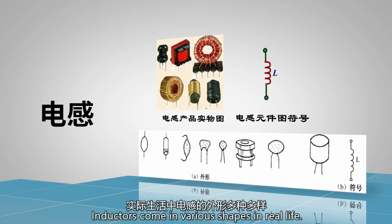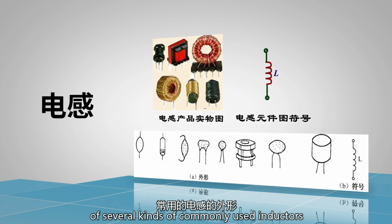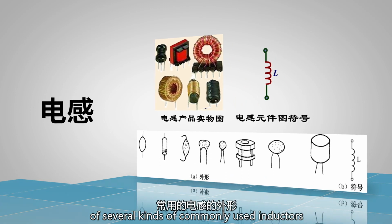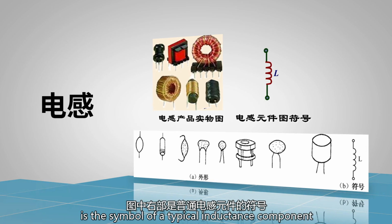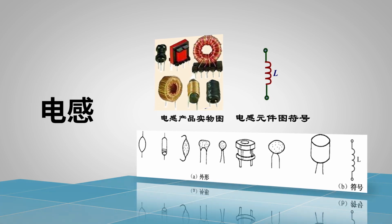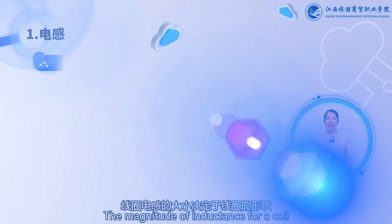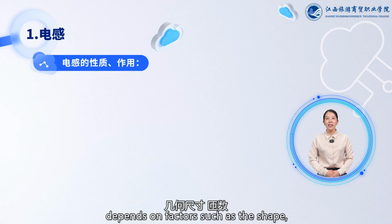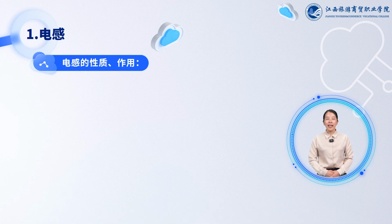Inductors come in various shapes in real life. The left part of the picture shows the shapes of several kinds of commonly used inductors. The right part of the diagram is the symbol of a typical inductance component. It is often represented by the letter L. The magnitude of inductance for a coil depends on factors such as the shape, geometry, number of turns, and magnetic permeability of the medium used.